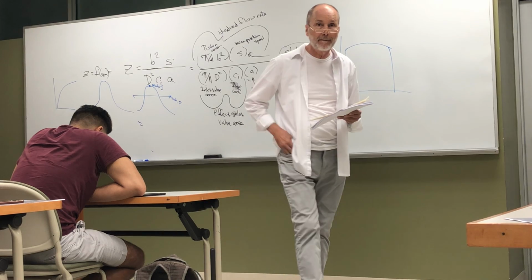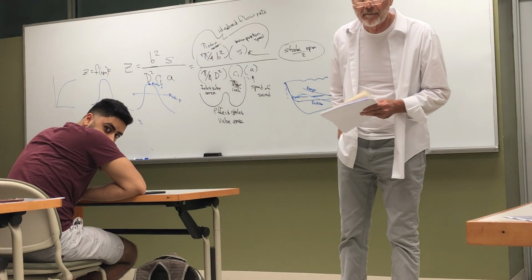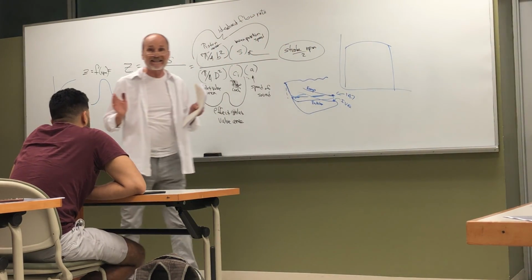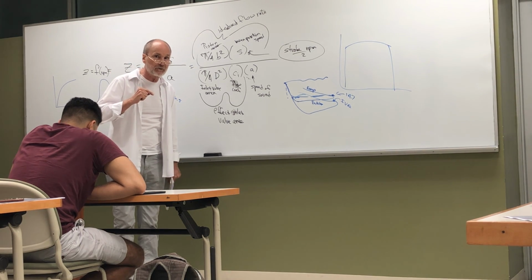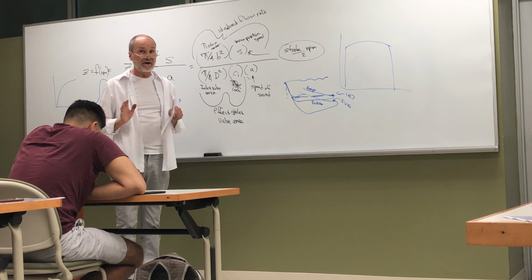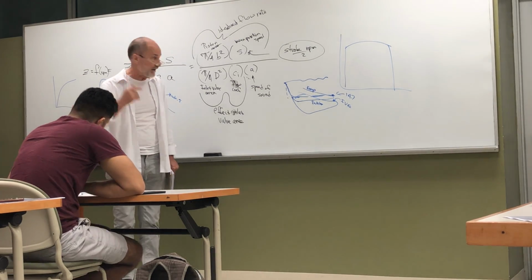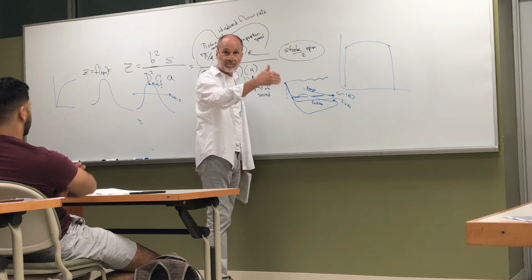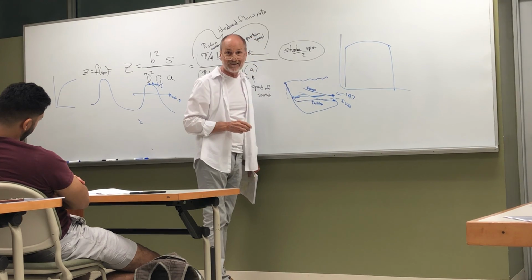Will you explain one more time how come, as you raise the Mach index number, we're getting less and less time to fill the cylinder? If we go from Mach index 0.2 to Mach index 0.4, we now have to fill the cylinder in half the time. To fill the cylinder in half the time, we're going to have to go to a lower pressure. And as we go up in Mach index number, we have to stay at this lower pressure for a longer length of time.